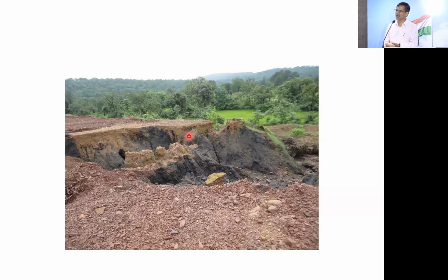So we tried to convince them, and then we protected it with a short-term measure. We calculated how much the depth should be, and then we analyzed that. The computer will do the analysis, that is not a problem. But first you have to invest in what you have to go for, like putting on the topsoil. On the coal overburden, they did not have it initially. If you are going for plantation, I always said at that time, you have to give a minimum of 1.5 to 2 meters of natural soil.